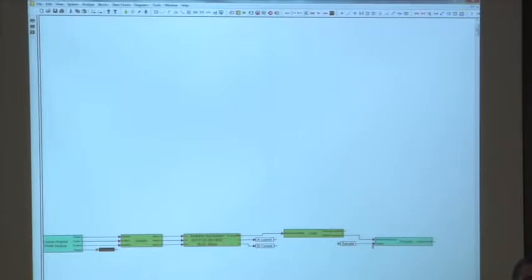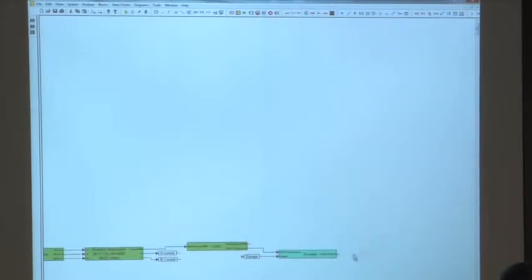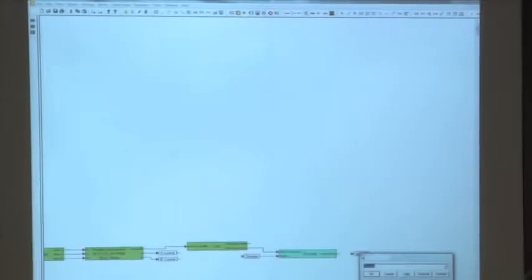All right. Now, we're almost ready to close the loops. Take the angle output of the encoder module, and go up to the VAR tool again, and drag down a variable for the output of that. And we're going to change that to be, instead of variable, we're going to call it angle. And then connect that to the output block of the encoder.